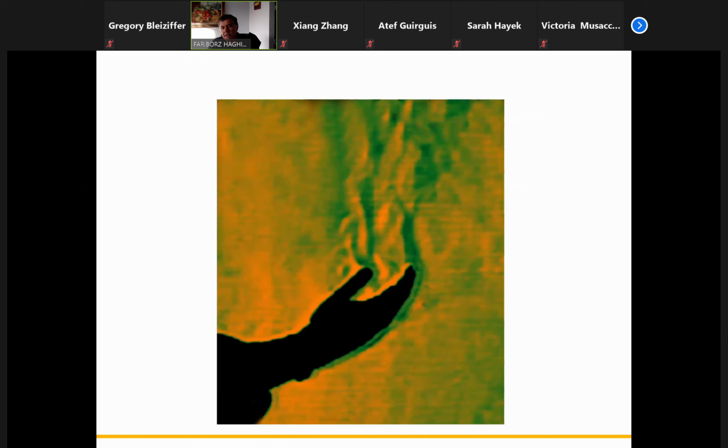This is the way you and I dissipate heat from our body. Inside our body, heat is generated at around 65 to 70 watts. All of it dissipates into the environment, and that's by natural convection, okay? My skin is around 37 degrees, and the air is 20, therefore that heat is generated in the living environment, okay?